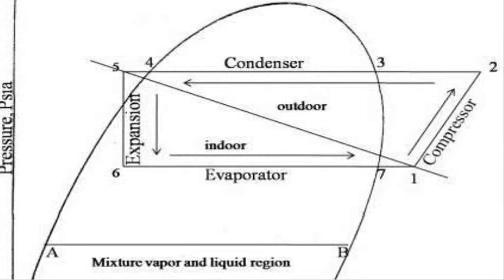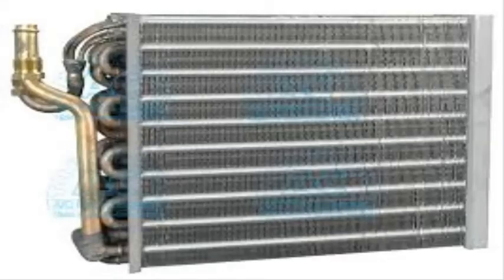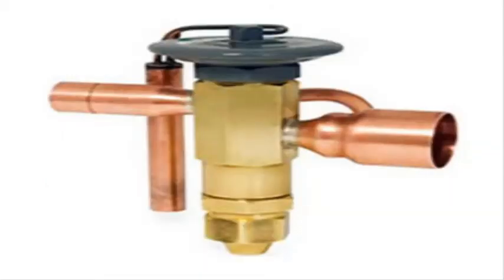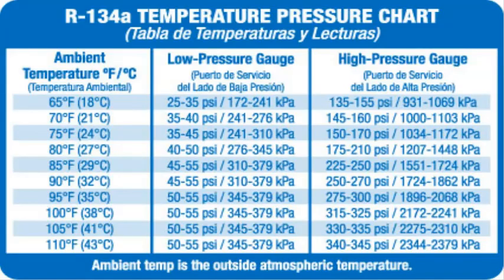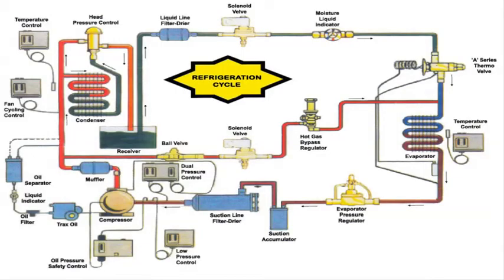In a refrigeration system, all 4 major components, such as the compressor, condenser, evaporator, and expansion device, must be balanced and selected properly as per the design load, normally called the tonnage of refrigeration, and all these components must be connected with suction line and discharge line of suitable material such as copper or mild steel.